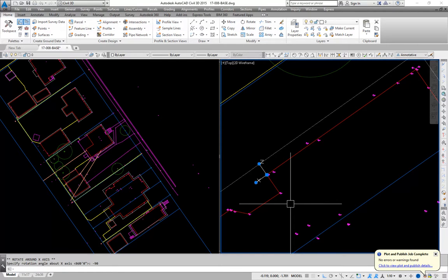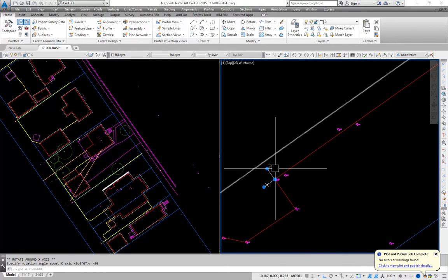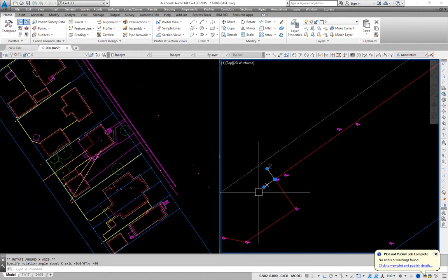So let's see what happened now. You can see that z is now pointing this way, x is this way, and again the right hand rule, where you open your right hand with your thumb extended, you start from x and you turn your hand to y and your thumb is pointing towards z. So right now, if I do that exercise, y is coming out at me, and that's exactly what I want.